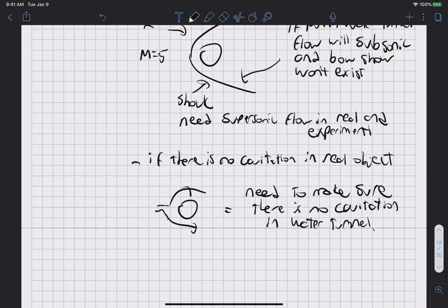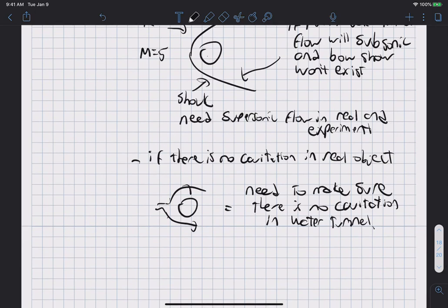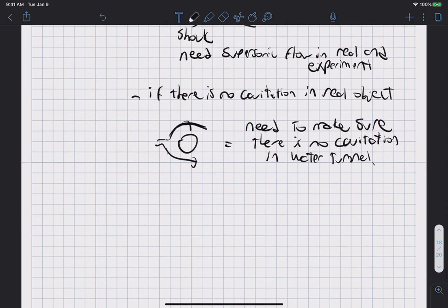Okay? So, in other words, if you are measuring the drag going over a sphere, and by plopping it into a water tunnel, you have to ensure that there will be no cavitation of the water as it goes over and around that object, which can happen, or for a pump or something like that. And similarly, another thing that can go wrong is sometimes you want to measure the drag force or something like that on an extremely tiny sphere, like a tiny little particle.